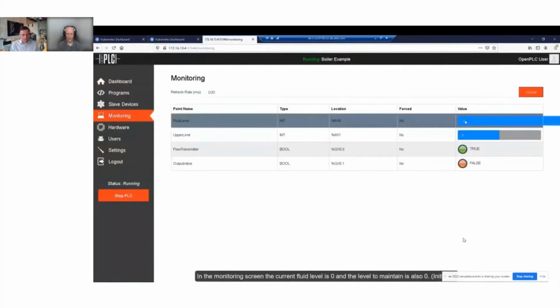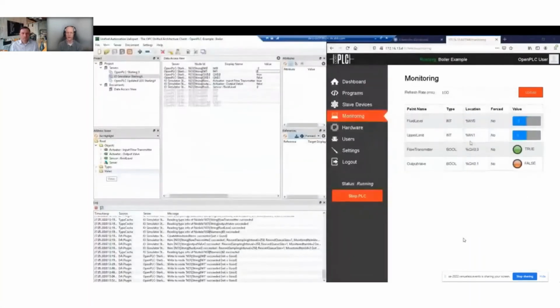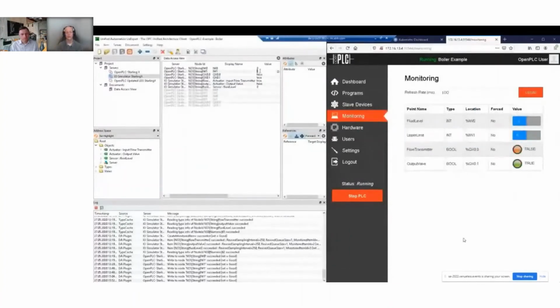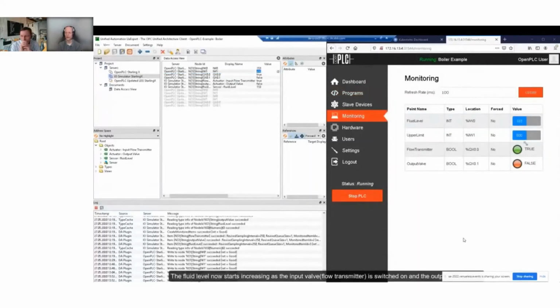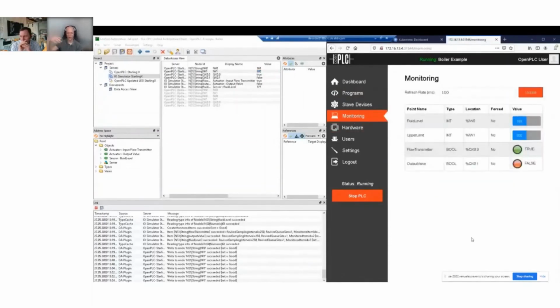And there you see the engine is now started, but it has not been initialized. So we use an OPC-UA client to supply a set point to the algorithm to say, okay, let's fill the tank to 600 centimeters. And then the control algorithm kicks in, and you see the fluid level is slowly rising up to the 600 centimeters. And once it's there, the controller controls the valves that regulate the input and output to keep the level at 600 centimeters. Yeah, so the state is reached now. We have sped it up a little bit. And now the controller tries to keep the level constant.